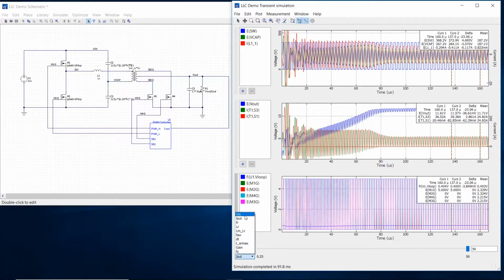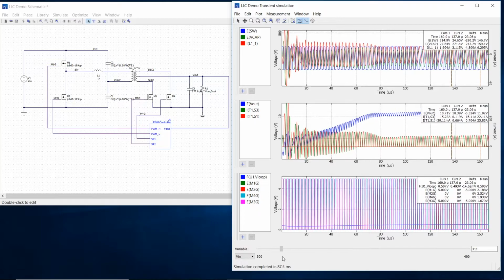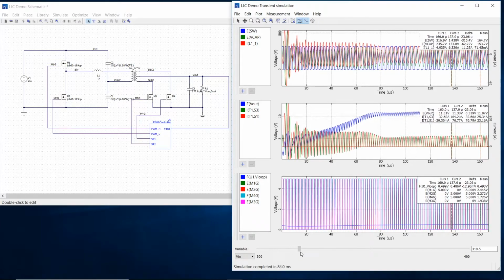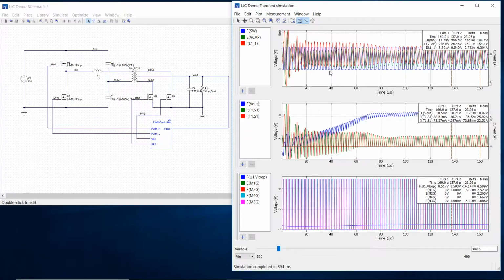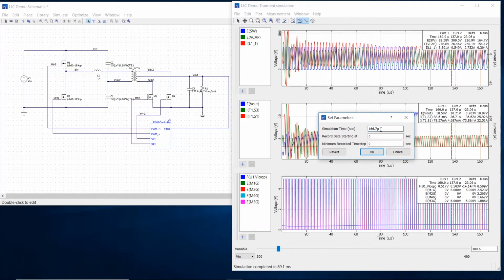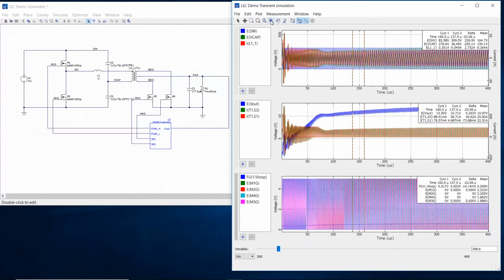Let's look at the input voltage regulation. At low line, the output sags. Well, it has a long tail. Let's see if I can speed up the controller. I'll start by increasing the simulation time to 400 microseconds and fitting the data to the window. There's a slow tail in the output voltage, so let's fix this. I'll hide the measurements and cursors.